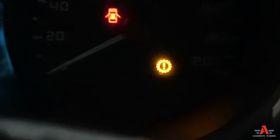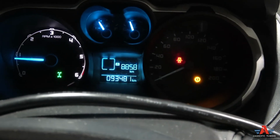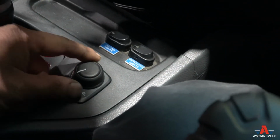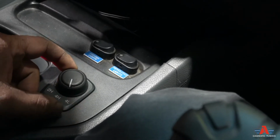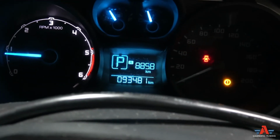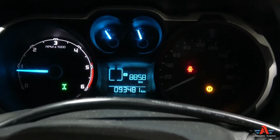Also here you got that gear with the exclamation mark sign. So this is the issue with the car, and you cannot select four-wheel drive at all. So right here is your four-wheel drive buttons. If you change that to 4 low, 4 high, 2H, nothing changes on the dash, and you can't engage four-wheel drive on this car. I think that's what the customer said, right?